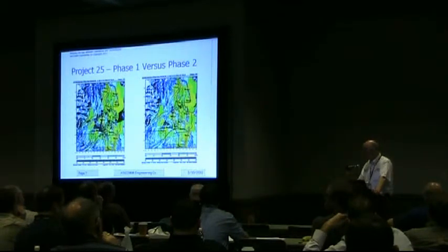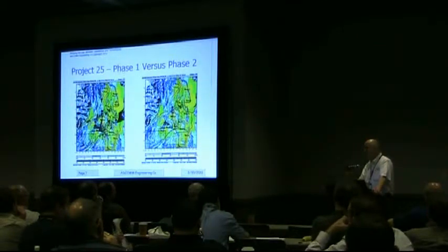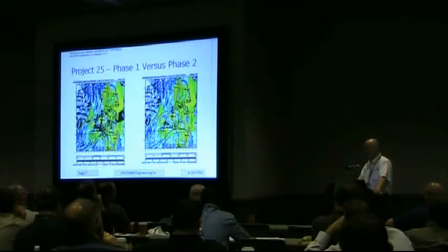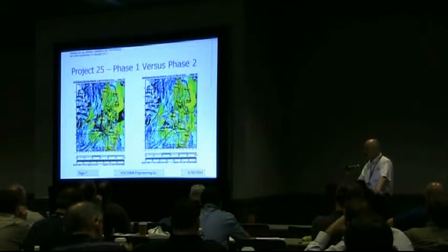Our assumption here is that the control channel will continue to work, at least reliably enough to be able to make the voice channel at 12 kilohertz work. Whether that actually works out or not, we don't know yet, but that's where we're going. Our experience with phase 1 systems has been there are places where the radio will decode the control channel okay, but you still don't have reliable audio, even in today's systems.